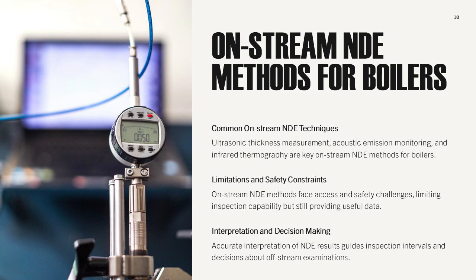On-stream non-destructive examination methods are limited by access and safety constraints but can still provide valuable information. Ultrasonic thickness measurements, acoustic emission monitoring, and infrared thermography are commonly used. Inspectors must understand method limitations, accuracy, and suitability for specific damage mechanisms. Proper interpretation of on-stream NDE results supports informed decisions regarding inspection intervals and the need for off-stream examination.